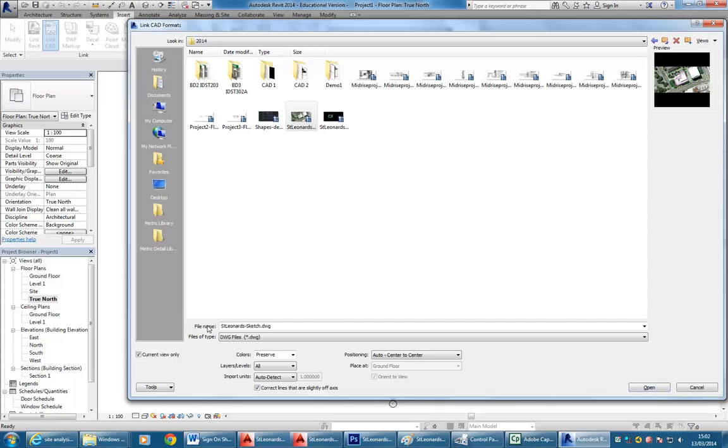And oh no, sorry, we've got. So I showed you last week to turn that off, didn't I? Which way did I show you? With it off? Yeah, off because we're setting True North with it. Yeah, look, generally 2D things you want it on because it's more of a graphical overlay when it's 2D. But this is just the thing with True North. It's better to leave this turned off, I mean, because of the way it carries through the other views. I'm going to rotate things, and I want it rotating in all the views. So it's just for things to set True North that you do it differently. But normally, the general rule of thumb is have that on for 2D things, have it off for 3D things.